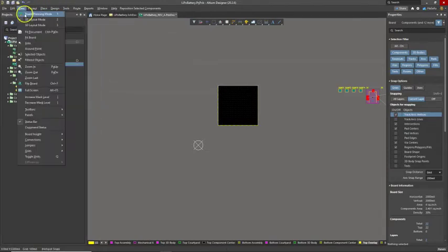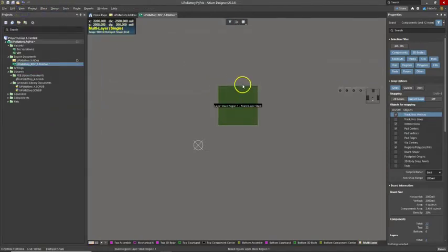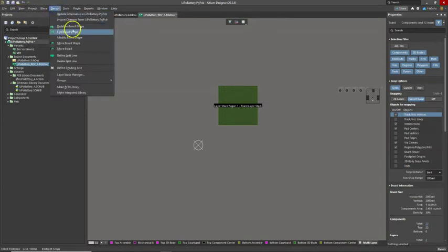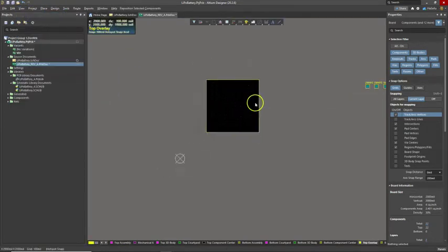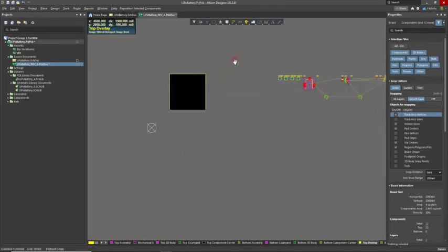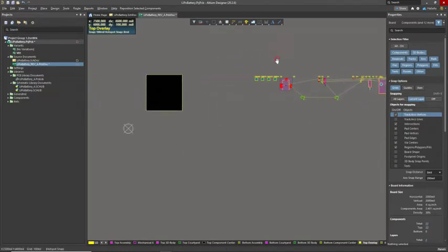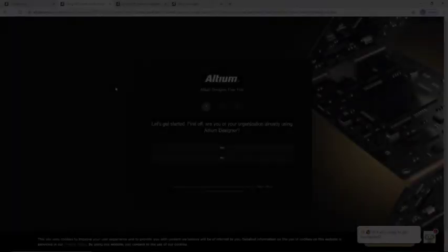Well, first of all, view, then board planning mode, and then you can do a lot. You can do the design, redefine the board shape, but we won't do all that. Let's go back into 2D layout mode. Now, that's how we set up our printed circuit board or PCB.